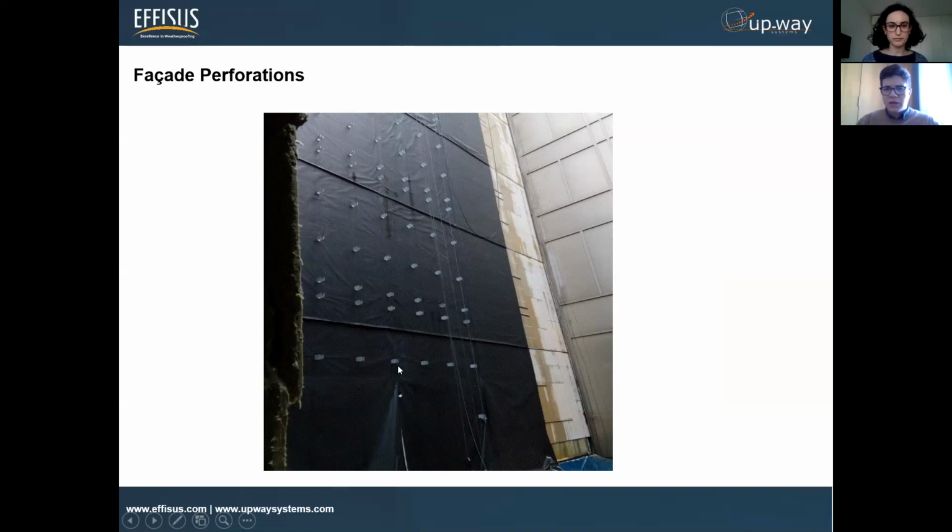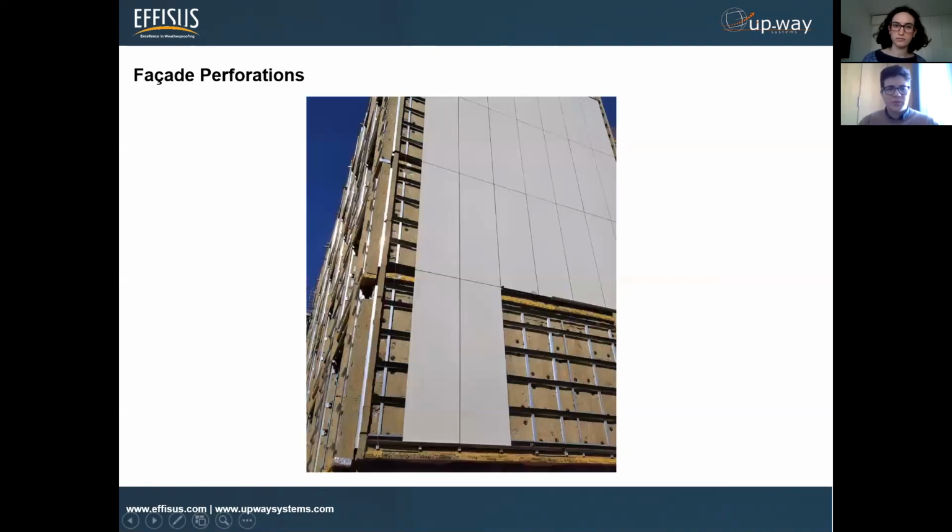How do you assure that you have no leakage inside for the board itself or the insulation itself, when it's just a cut open hole here? Again, this will lead to a series of problems. The main one being a leakage inside the building. Another one I can mention is loss of energy efficiency. We all know if it's a wet insulation and having this point opened, all the open gaps there will not perform very well. Of course, having a breather membrane in this case will prevent most of this, but we need to look into details of how we actually need to seal this type of perforation.